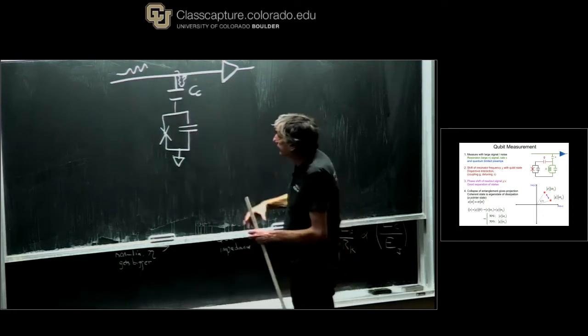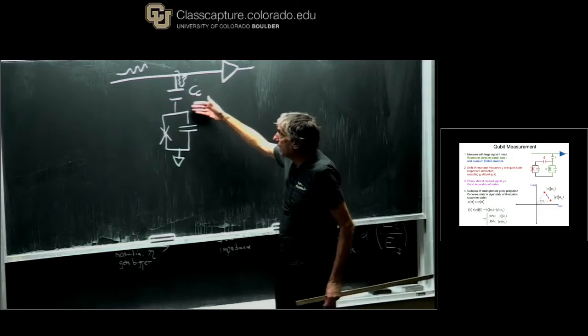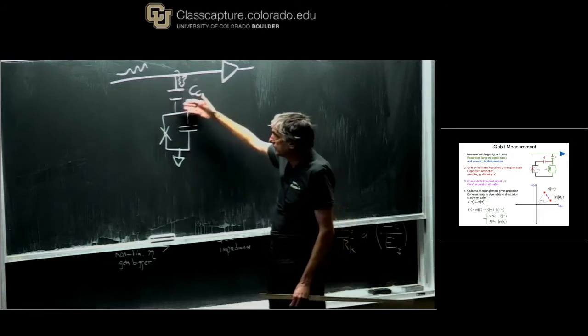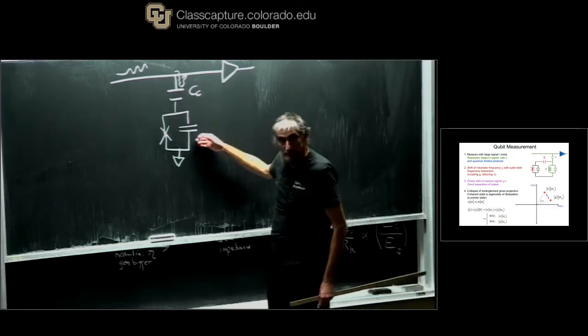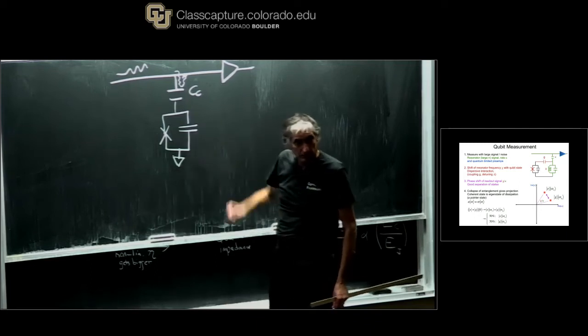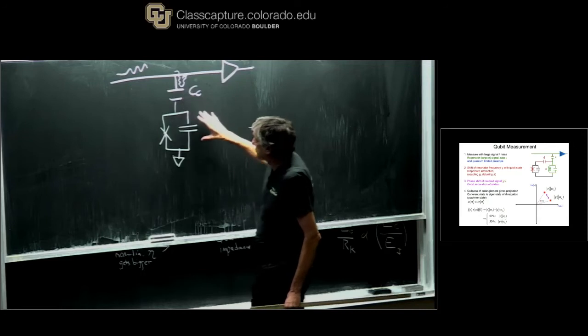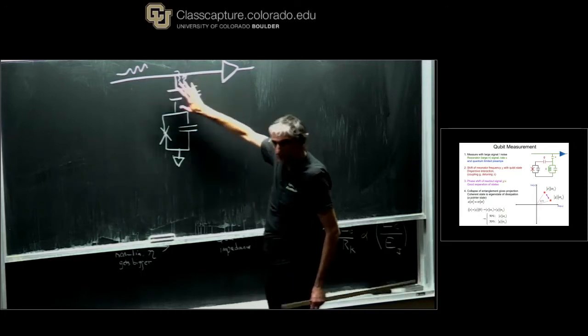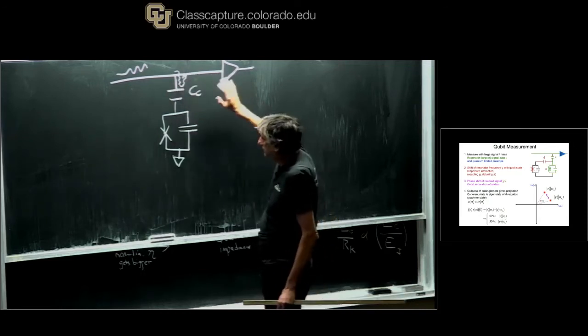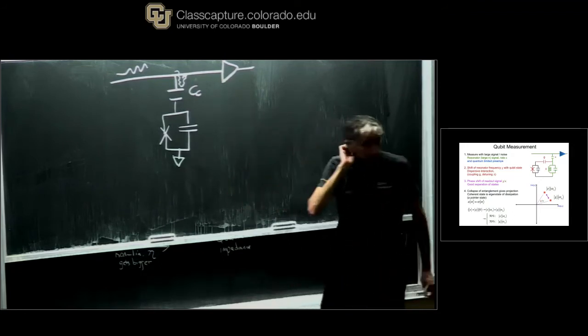So we're going to get a measurement, but when we're not measuring, this measurement circuit is going to damp the qubit and cause the qubit to be bad. Remember, there's a 50 ohm resistor and a coupling capacitor. If this is strongly coupled, to be able to see this well, it's going to get messed up. Okay?